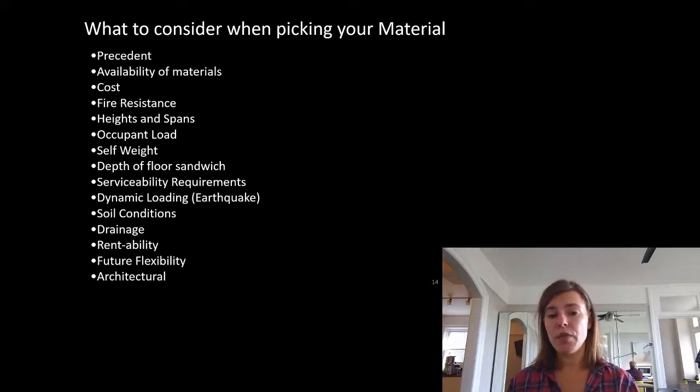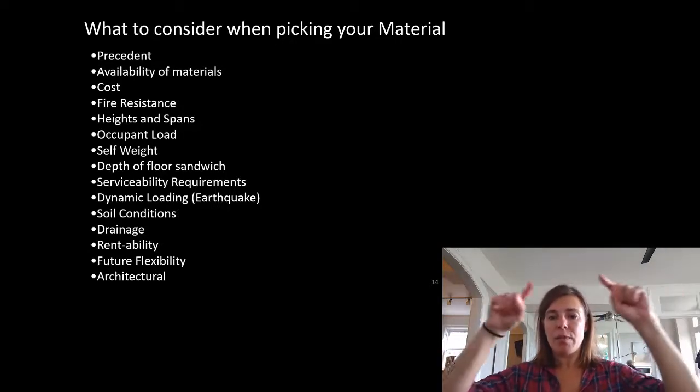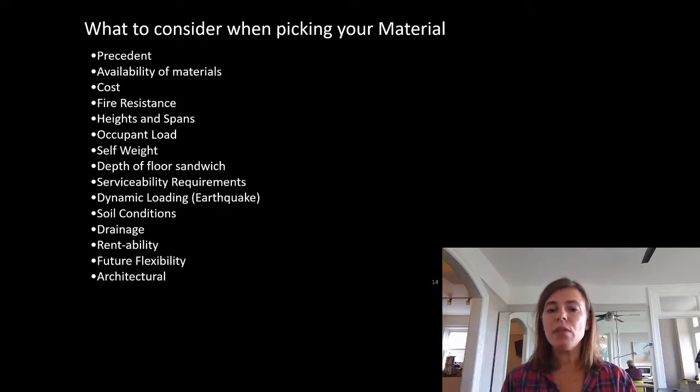Serviceability requirements. If you have something that needs really highly refined serviceability requirements, I think I told the story of Gold Ring, where we had an MRI on the 4th floor supporting an Olympic weightlifting floor below it, and we were actually hanging the 3rd floor. So it wasn't like the vibration had to go out and up the columns and come back to it. It was literally suspended from where the MRI was, which is highly sensitive to vibration.